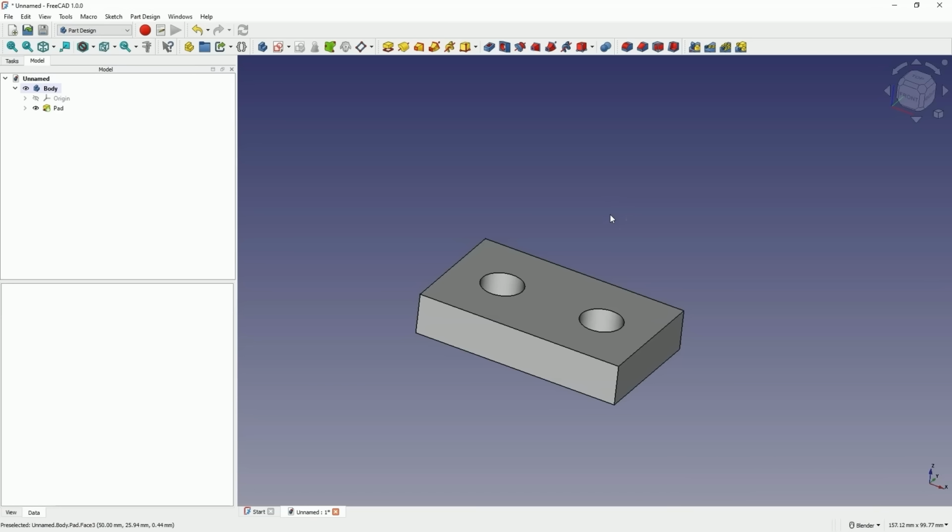When it comes to creating a solid based on a sketch, this is the basic operation of creating a 3D solid. And the second basic operation related to creating 3D models is an operation that allows you to remove material from a solid based on a 2D sketch, and this is the pocket operation. This operation also works on 2D sketches, and we will create another sketch for such an operation.